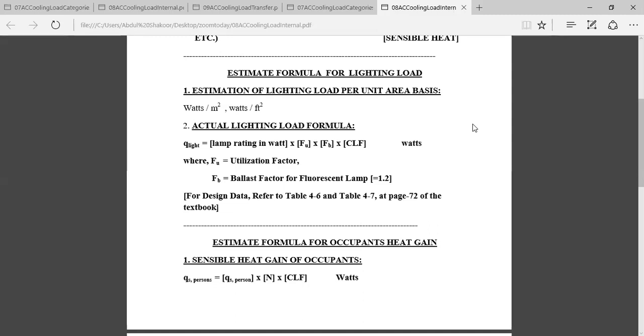If you don't know, and the electrical design is not available, sometimes electrical engineers do not perform the calculation. They say, "I'm not ready," so you should not be waiting for him. Just take on a floor area basis what the electrical load is. Electrical load for a residential building or office building is usually taken as 2 watts per foot square of the floor area.